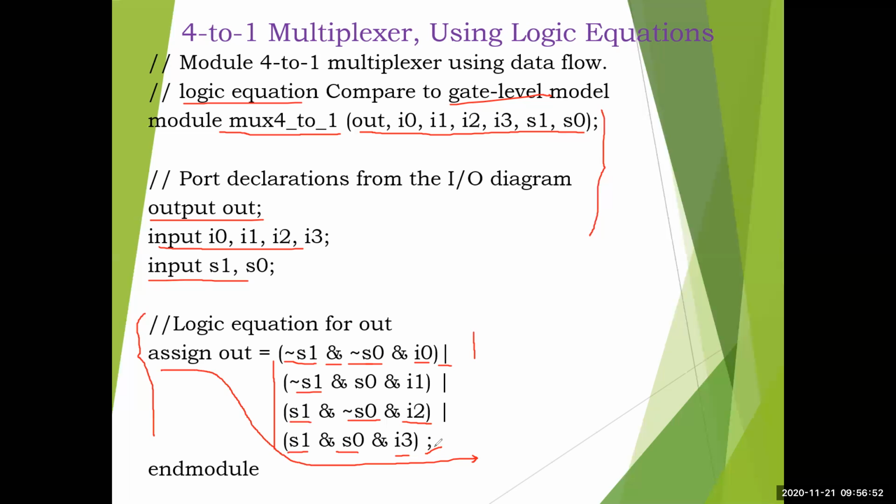We used this in gate level modeling, but now we are using a single expression with the help of operators. When you run this in a CAD tool, a logic synthesis tool will convert this into a Verilog gate level model. At the lowest level it is going to take that, but as a circuit designer we are not going to do that. So we are writing the program now at data flow model.